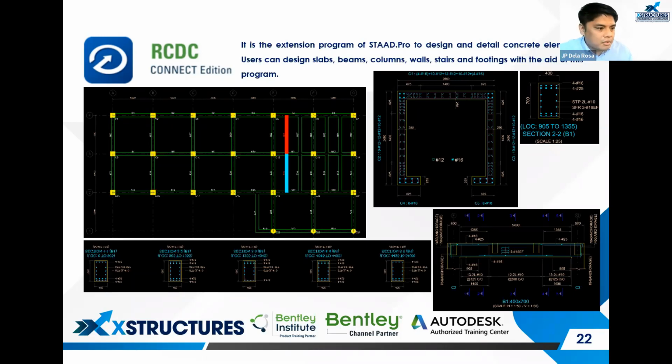The images you're seeing on the screen are direct drawings generated by RCDC, high quality drawings produced directly by the program. What you need to do is just export it to AutoCAD and put on a proper title block, and that's it. So you will now have your drawing.